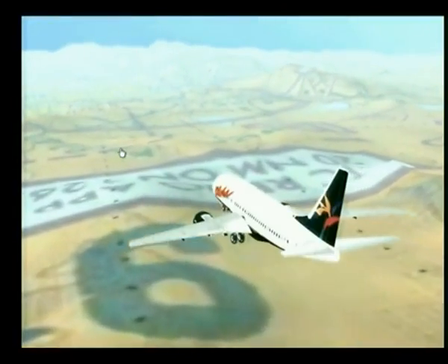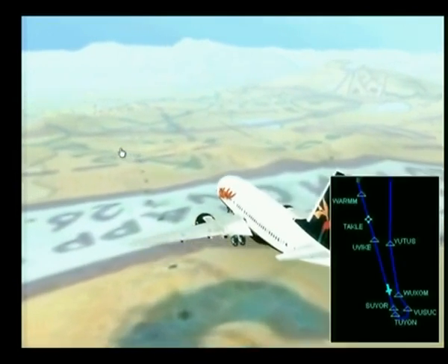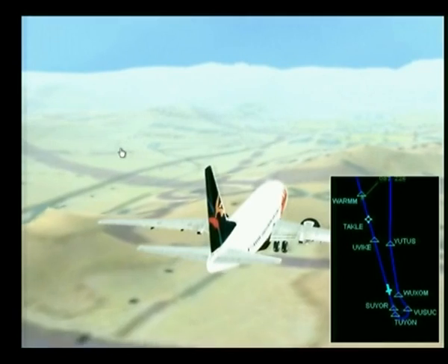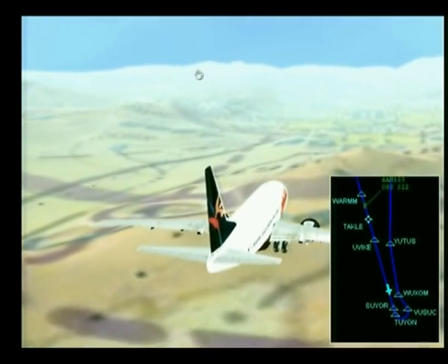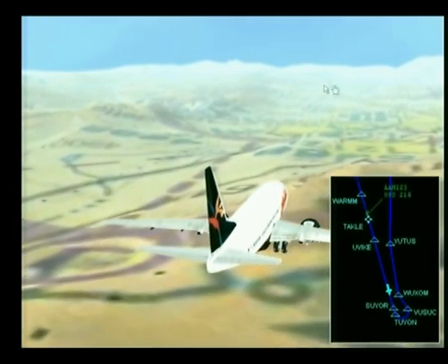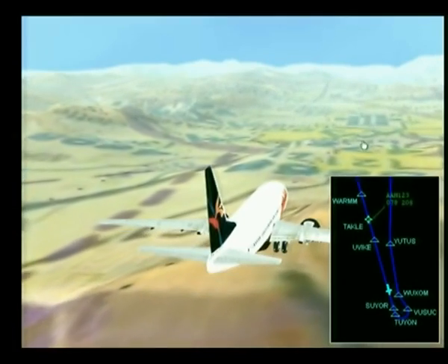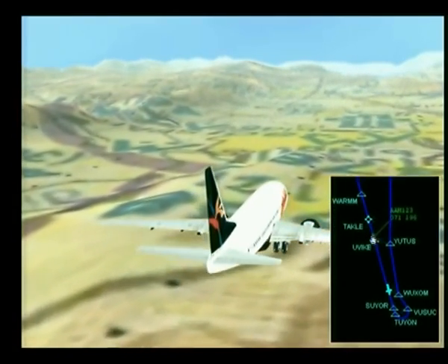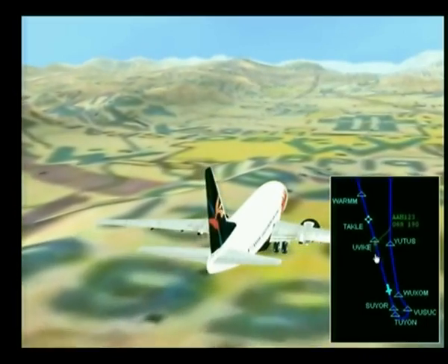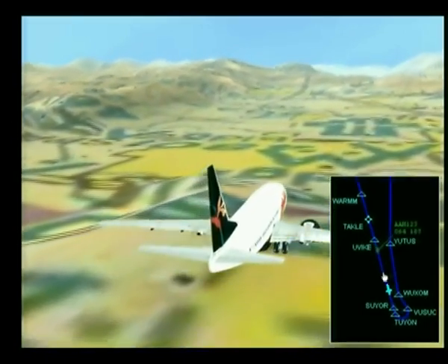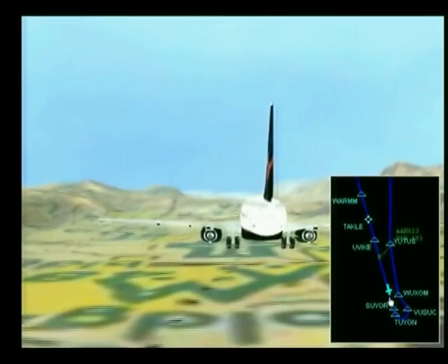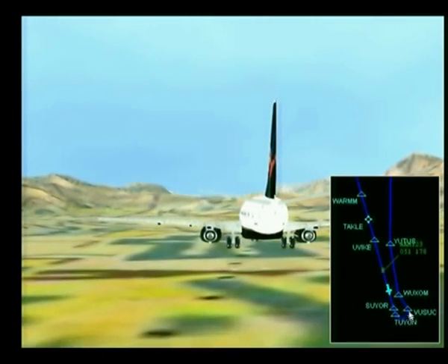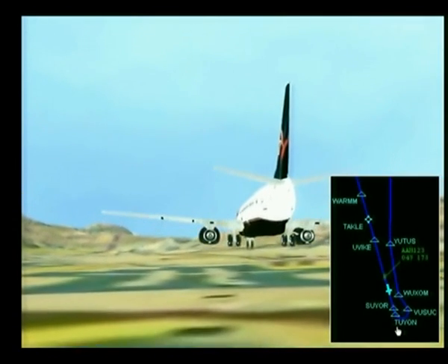This is the topography around Reno Airport as we're approaching the 16 right runway to the left. You can see the incredible mountainous terrain. This is what we're going to be avoiding over here on the miss. Down in the valley here are the runways. Here's 16 left and 16 right. You can see the green pipper here as the airplane hits these waypoints on the ILS final. When we get here, it's going to go to LNAV, follow these missed approach waypoints and make this turn here. And it's really quite dramatic.